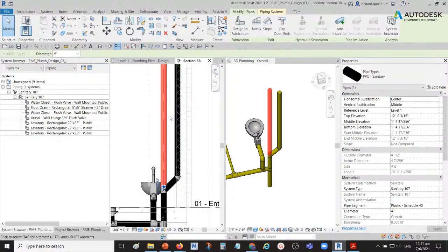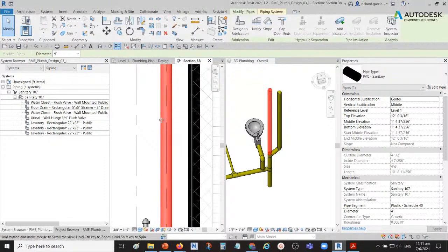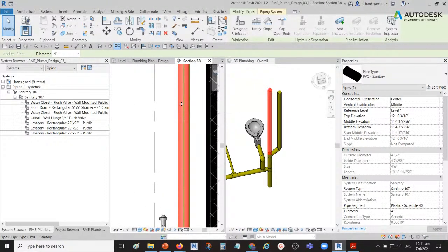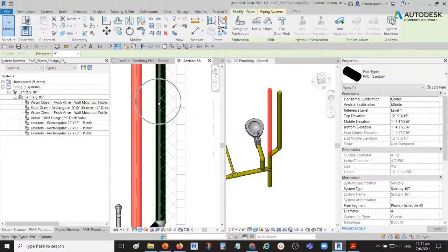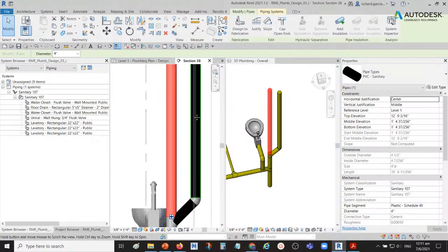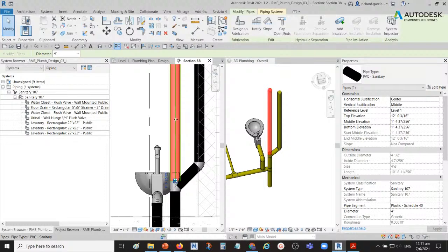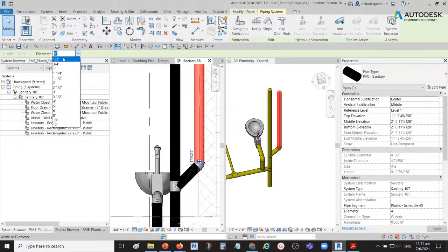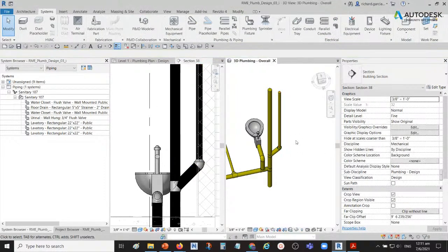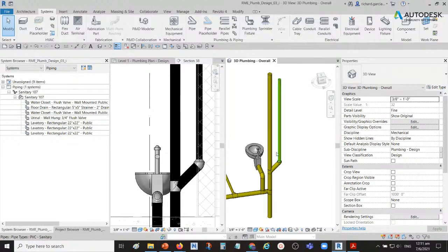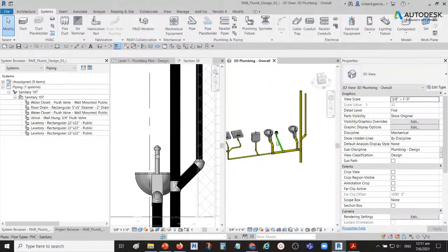Okay, just make sure your pipe for the main stack. The standard that we are using is 100 mm. And then for the vent, we use 65 mm. Okay, so I think this one is just the same. So this one is what? 4 inch. Okay, so this one should be 2.5. Something like that. Okay, right? So that is going to be your vent.